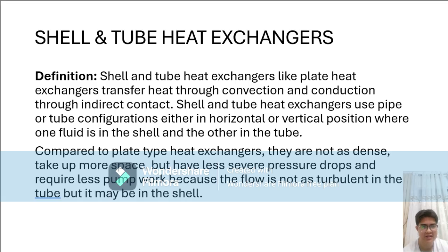This was not addressed before, but since a plate type heat exchanger does not have tubes flowing through its channels, what it has instead is an alignment of holes on the corners of the plates that act as a virtual tunnel, a manifold, where the fluids, hot and cold, are pumped through it, and they flow up or down.